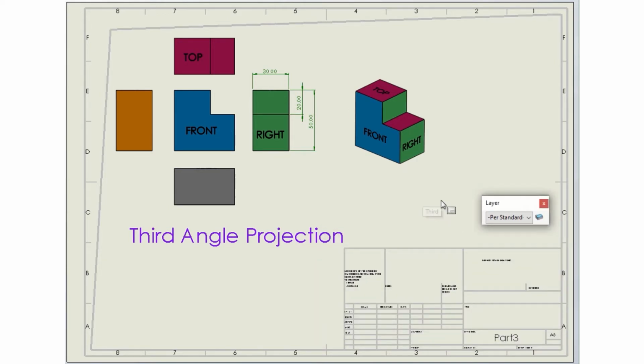You can add as many as you want in Solidworks and in most software, and then you just assign different elements to different layers. You can change the colors, you can change their behavior, and that makes it easier to view and print the things that are important at that particular time without losing any more information.